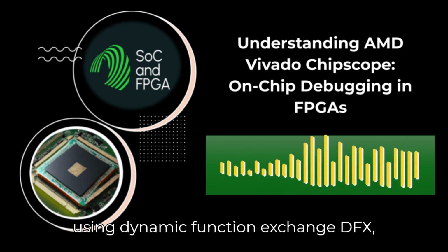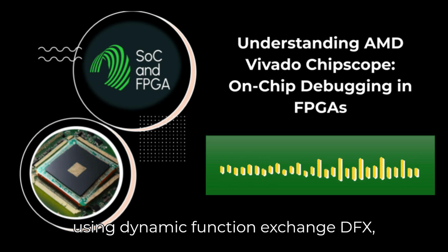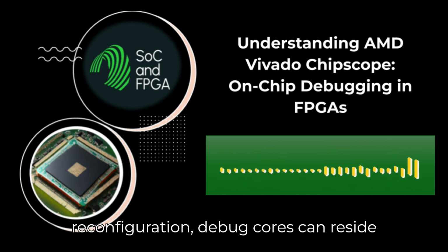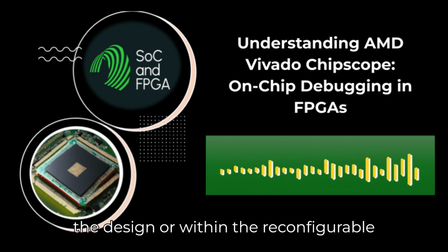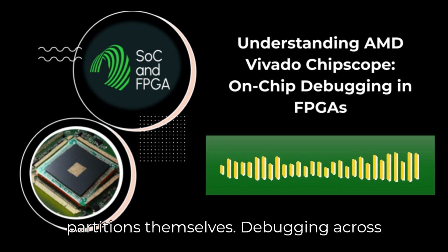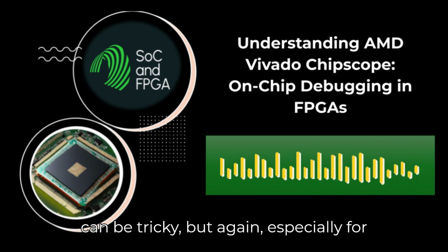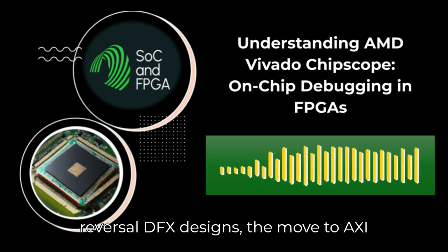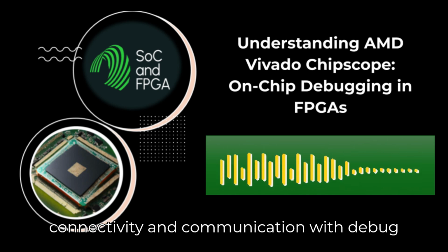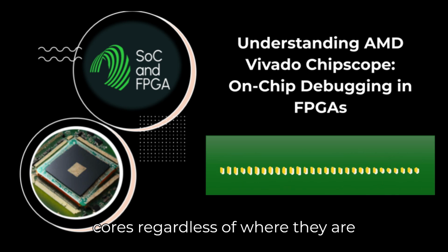And for designs using dynamic function exchange, DFX, formerly known as partial reconfiguration, debug cores can reside either in the static, unchanging part of the design or within the reconfigurable partitions themselves. Debugging across those static or configurable boundaries can be tricky, but again, especially for Versal DFX designs, the move to AXI-based debug helps simplify the connectivity and communication with debug cores, regardless of where they are physically located.